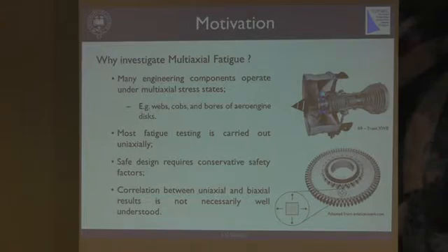We work a lot with Rolls-Royce, and in particular they're concerned about the disc of the aircraft engine, this disc here, and of course the stresses here are highly multi-axial, both in the web of the disc here, but also in the bore. They're quite complicated. There are thermal transients as well as mechanical loads and so on.